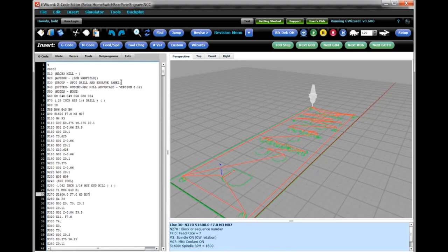One more useful thing to know about for the back plot, if you click this little button, it's zoom extents. That'll scale the back plot so you can see everything. If you get things too screwed up, click that. The back plot will also automatically update anytime you change anything, but you've also got a button that'll make it go through and completely redo the back plot.